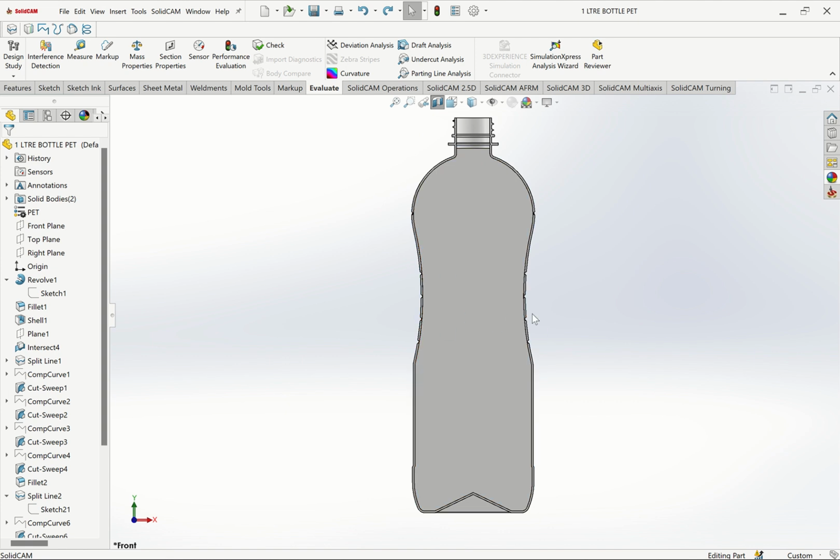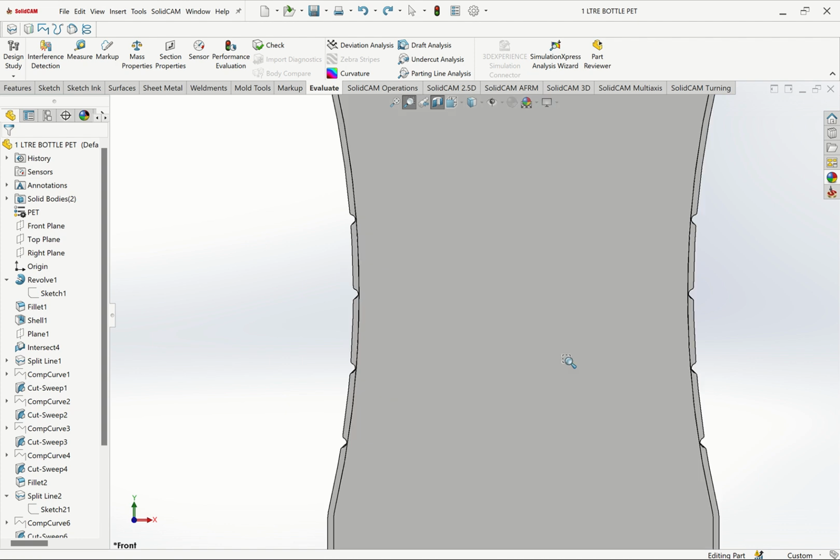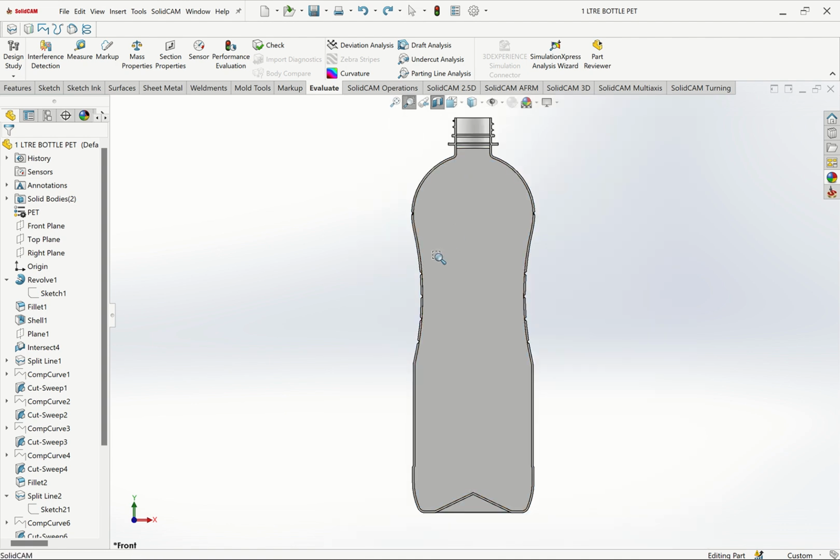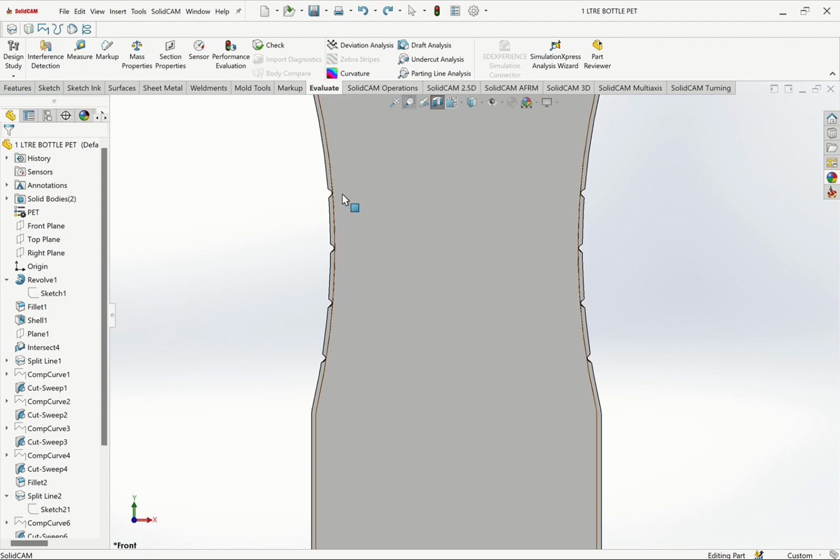Remember, this is not what I intend to do, but if I was to design it for a client, this shape should also correspond to the thickness inside, because the way it is, this part will be weak. So in case the client wants, I'm able to change this one. I'm doing it for the sake of training, but if the client wants the actual design, I'll change it so that this shape can also correspond inside, because the way it is, these points are weak points. It may not be as strong as I want.